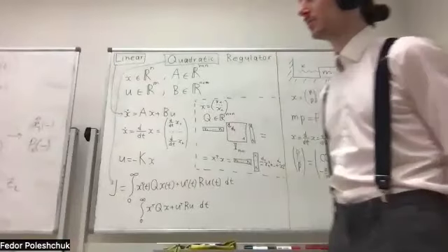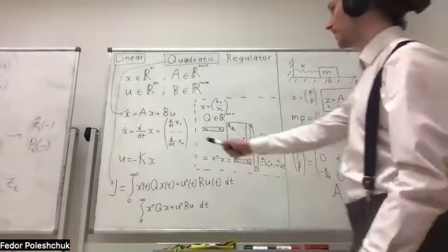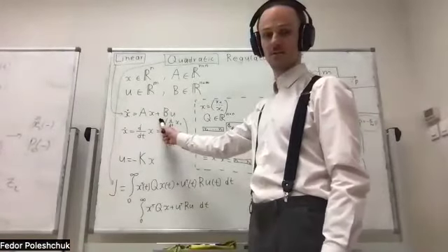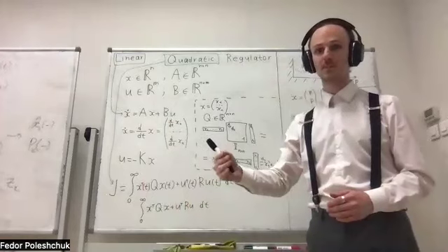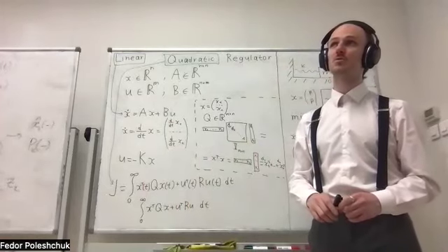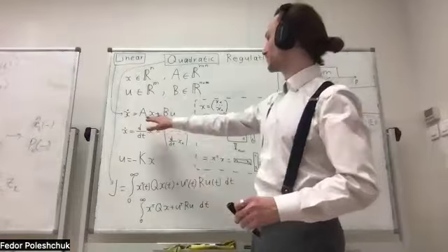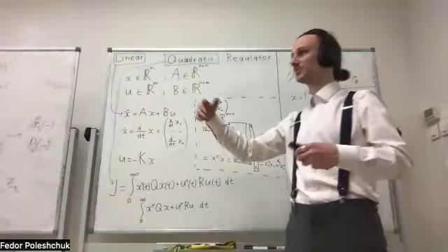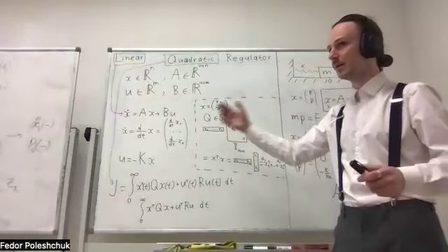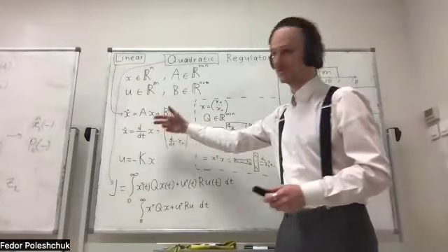You were saying before that you need to know more about the model for this type of controller. Is it because you need the state variables? We need the state variables and also the A and B matrices here. Then this is exactly the model. We have to know it. We are not usually supposed to choose it, because this is the characteristic of the system dynamics. It depends on the mass, and this depends on the elasticity, the stiffness. And the B matrix is the control matrix.